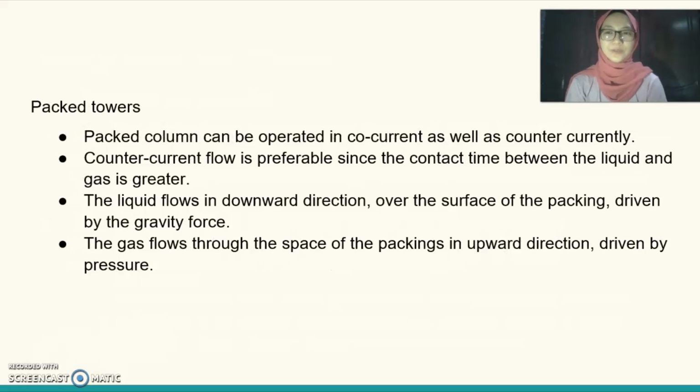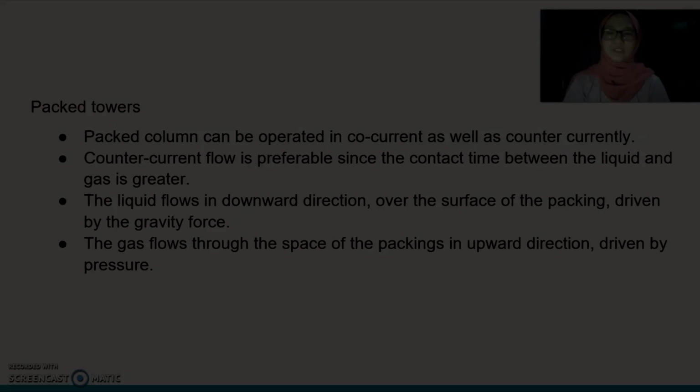For the packed tower, the packed column can be operated concurrently as well as countercurrently. Countercurrent flow is preferable since the contact time between the liquid and gas is greater. The liquid flows in a downward direction over the surface of the packing, driven by gravity. The gas flows through the space of the packing in an upward direction, driven by pressure.